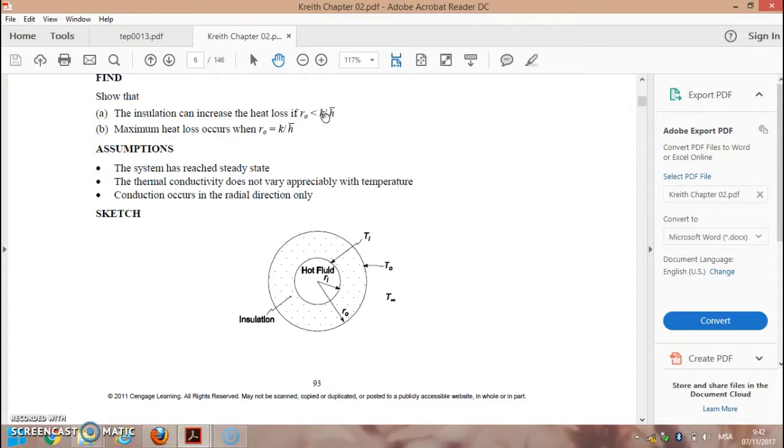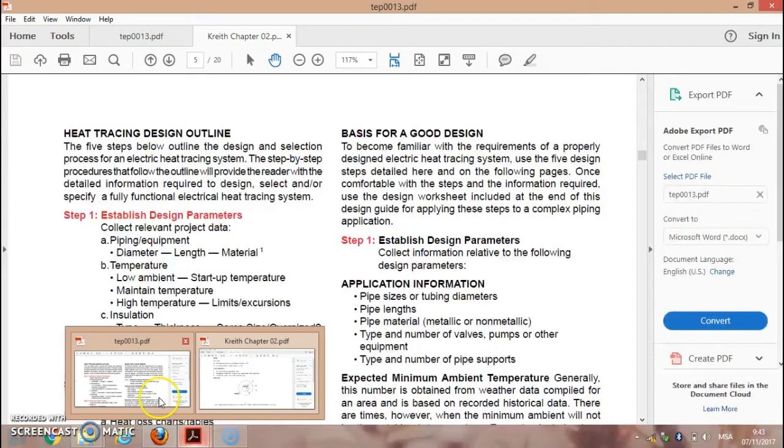I will explain about the K element, which is the thermal conductivity. The definition is a measure of the ability of a material to transfer heat. For example, if two molecules collide, energy will transfer from the hot to the cold molecule, and there will be a cumulative effect from all collisions between the net flux of both bodies. We call this kind of transfer thermal conductivity. Regarding the question, thermal conductivity does not vary appreciably with temperature. That's why the question didn't give us a specific temperature.